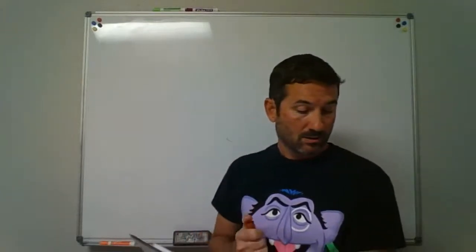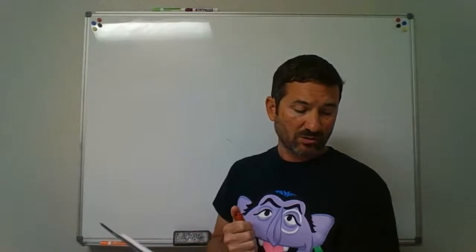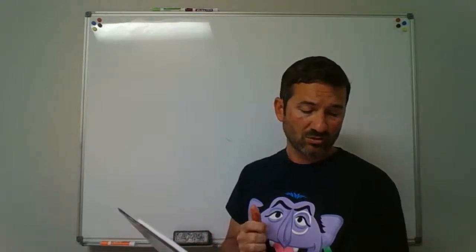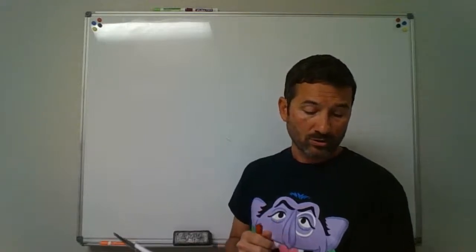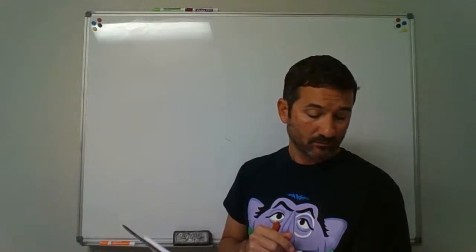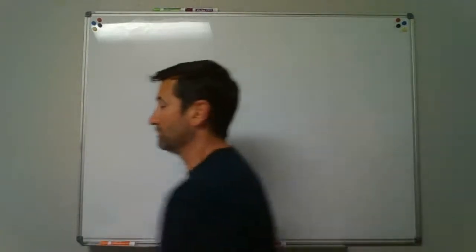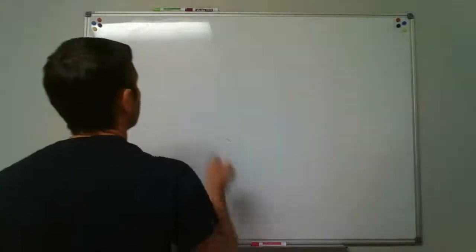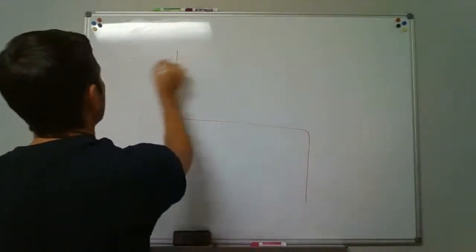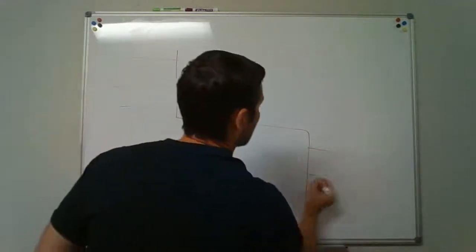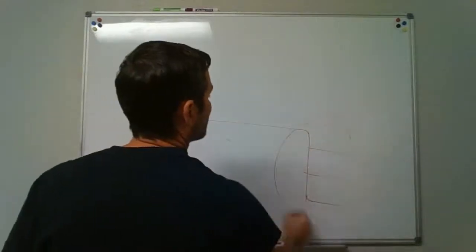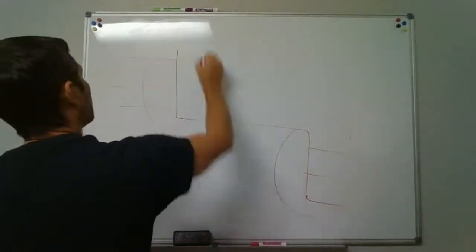Okay. The upper section of the drainage stack should be vented as a separate stack with a vent stack connection installed in accordance with section 904.4, which we talked about. The offset should be considered the base of the stack. So basically, they're saying we're going to vent this stack separately.